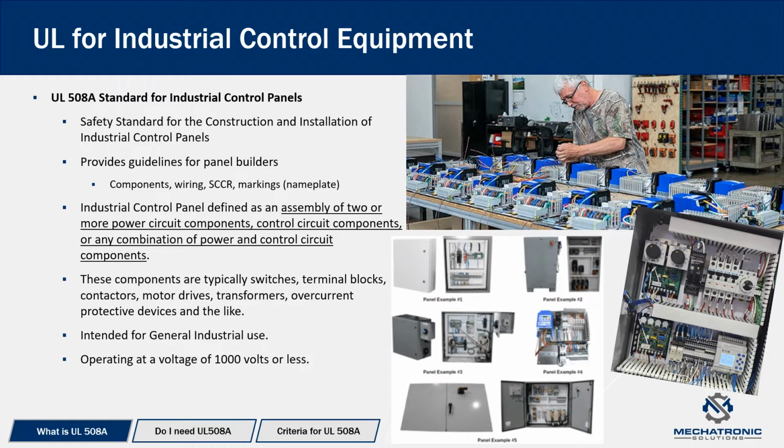So what is UL508A? It is the standard for industrial control panels. Specifically for the construction and installation of industrial control panels. It provides guidelines for panel builders, some of those being what components you use, the wiring, the short circuit current rating, markings, and where they go.